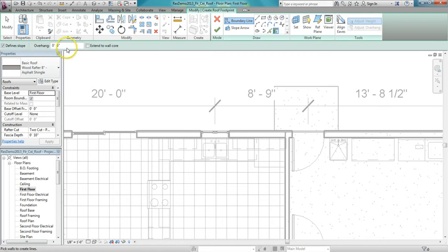And I'm going to have my 6-inch overhang again, and I have define slope checked, so I'm going to select this part of the porch right here. Now, to get my overhang, I need to set this offset for 6 inches. Okay. Then I'm going to turn off the define slope, and I'm going to offset 6 inches on either side here.